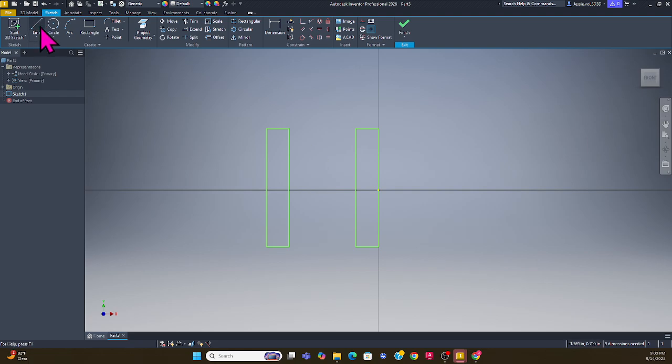All right. Like I said, we're going to do a letter N, so I'm going to go ahead and try to do something here. And I'm also going to show you something, maybe it would be a good time now. I'm going to use offset. I'm going to offset this this way. Let's say I want to offset it 0.05 this way, and then I will offset this the same 0.05 that way.